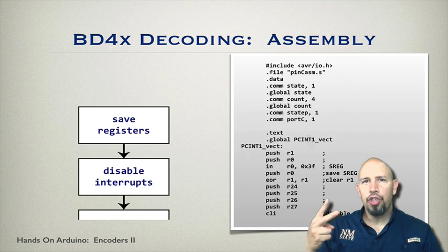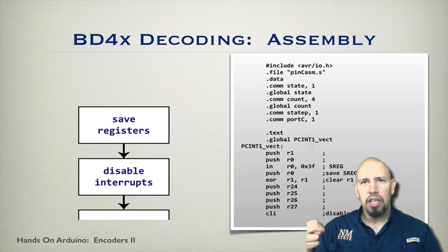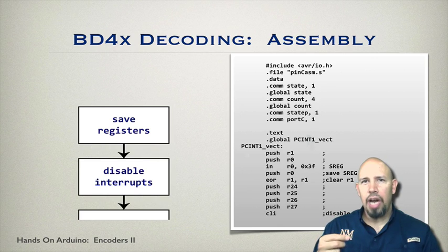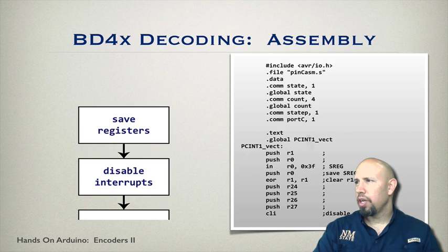Notice that we have two channels that can actually cause an interrupt because of the way things are defined. In our particular case with this digital pot, we're actually on analog pins 3 and 4, and so we need to work with port C in all of this, which corresponds to the PCInt1 vector.